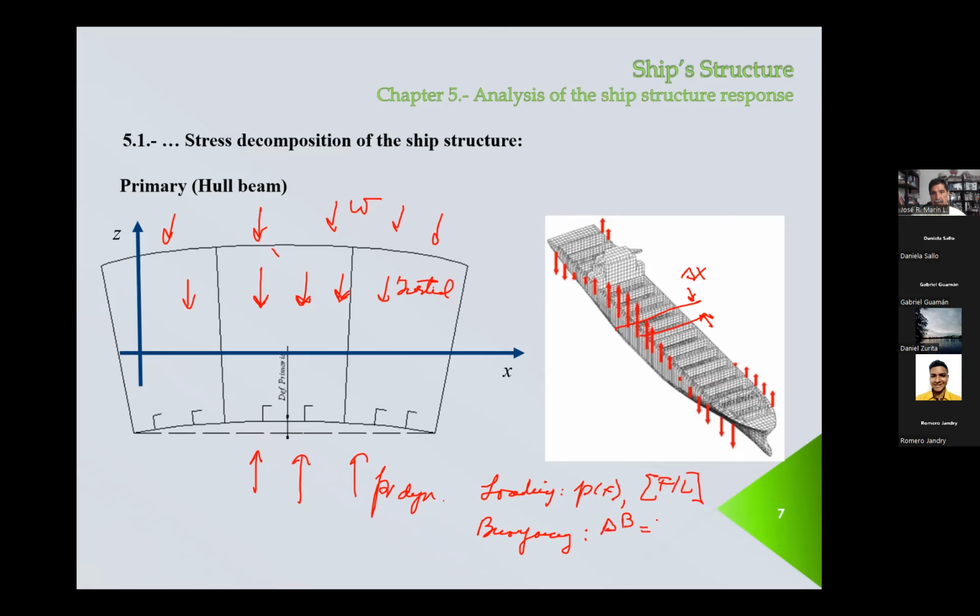So it's going to be equal to the area of the hull, multiplied by the length, which is delta X, and multiplied by gamma. Okay. Now, if we define B as buoyancy per unit length, that would be delta V large over delta X. So we put this on the left-hand side, and that's going to be equal to the area times gamma.